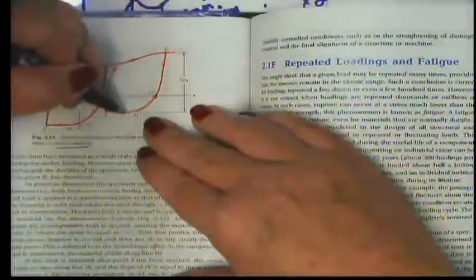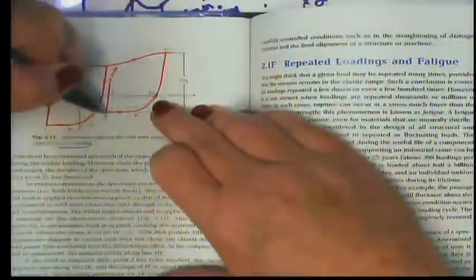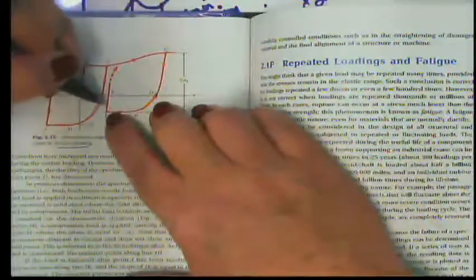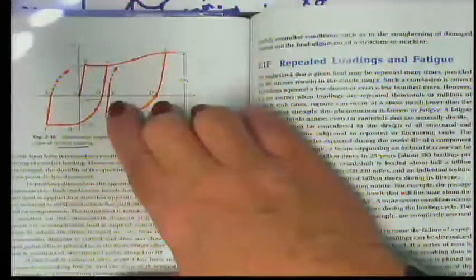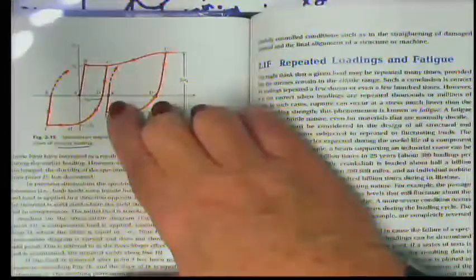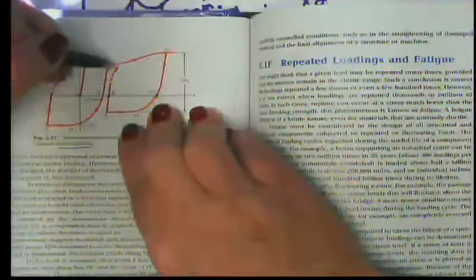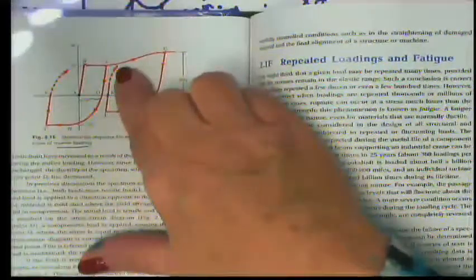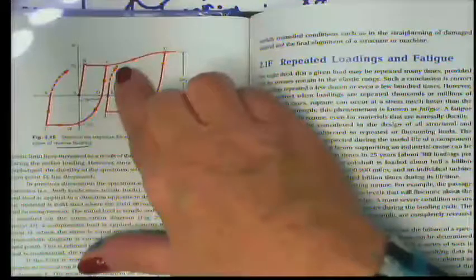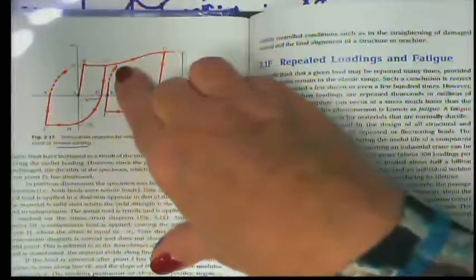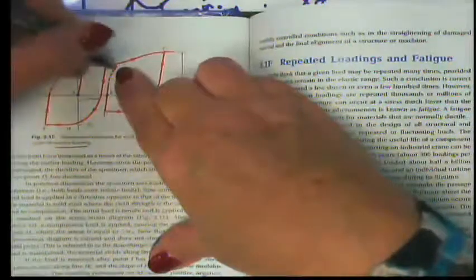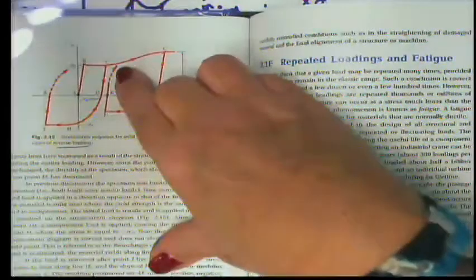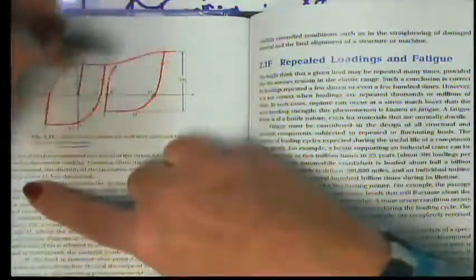So what we do is we depress it. We actually here would put it into compression, and then we remove the load again, and guess what? We're at 0 load, and now we have an intermediate length between the two. So then we increase our load a little bit, and the material has become deformed or has become structurally altered, like the hot paper clip, and it will break at a value below sigma yield. Okay, so that's what this curve over here indicates.